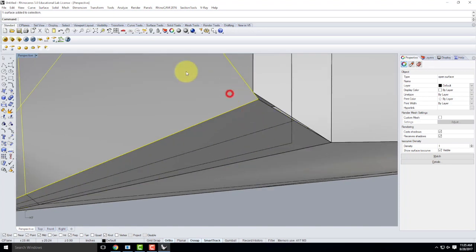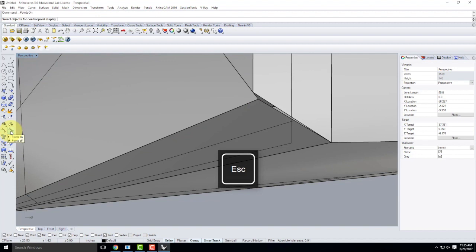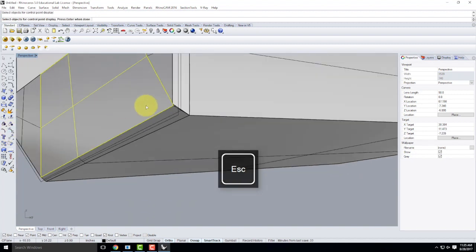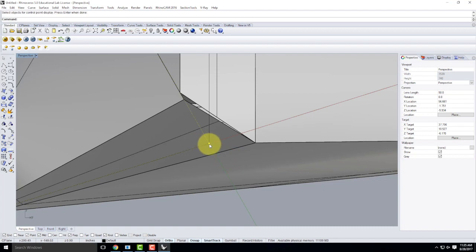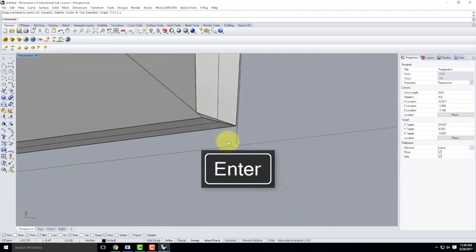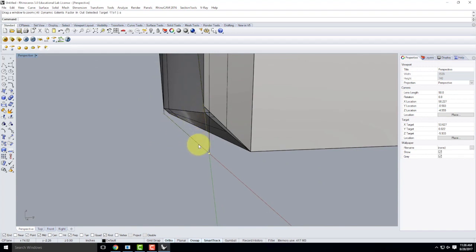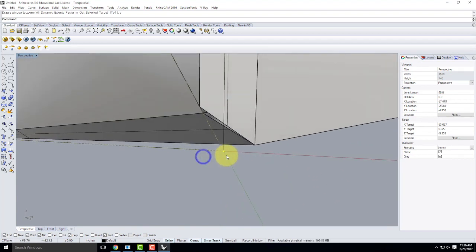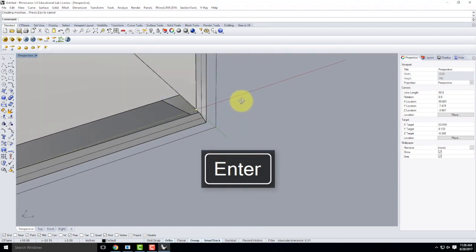So the first thing that I'll do is I'll take this first surface, and I'm going to come over here, and there's something called Edit Points. And I'm going to, oops, sorry, it's this one. It's Points On. I want points on for this object, and it'll give me a little point that controls the surface. Unfortunately, that surface point isn't, let me zoom selected for a second, so we're reorienting. It's in plane with the object, but see how there's a lot more to the object? If I were to just move that point to that point, I'd end up with a gap, and that doesn't work.